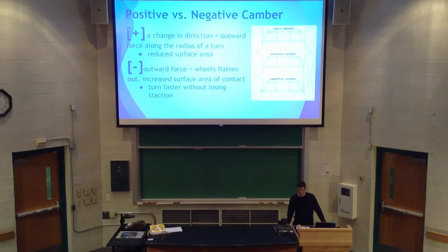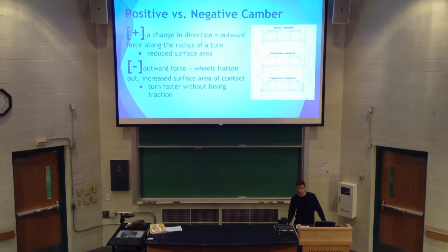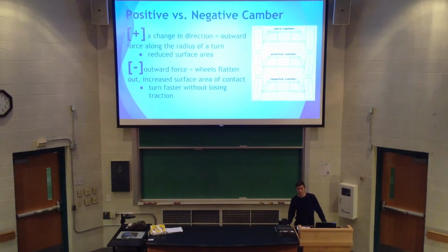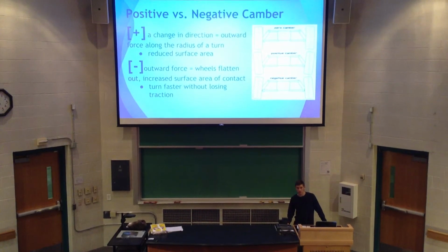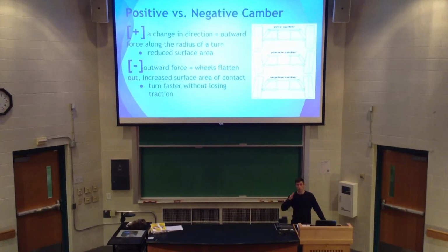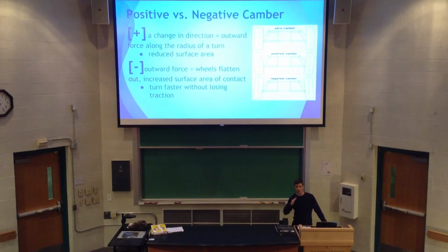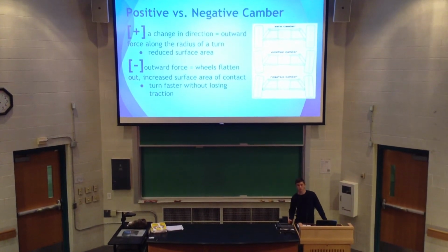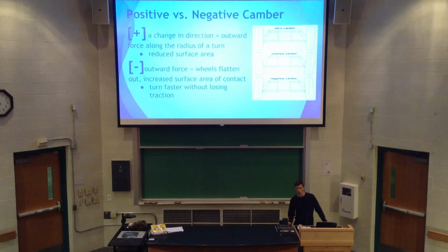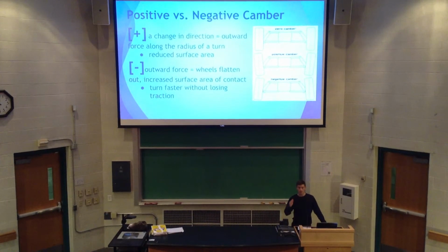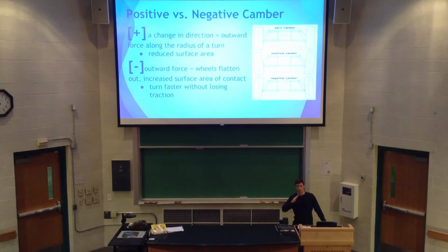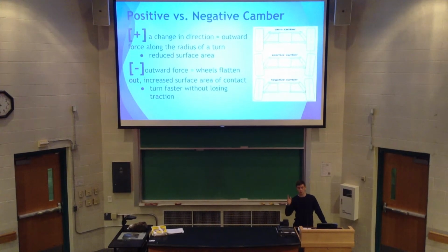For our suspension system, we made uneven control arms. We made the top one a little bit shorter so that the vehicle naturally rests with a little bit of negative camber, so that the top of the wheel will be facing inside. When the vehicle goes around sharp turns at high rates, the force will still be there, but instead of the wheel going outwards, it will go back into an upright position.